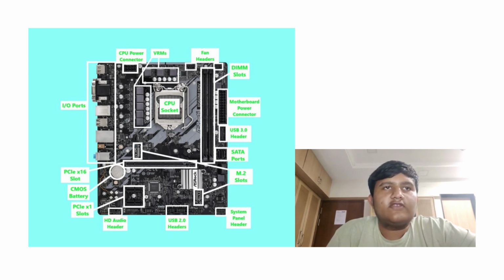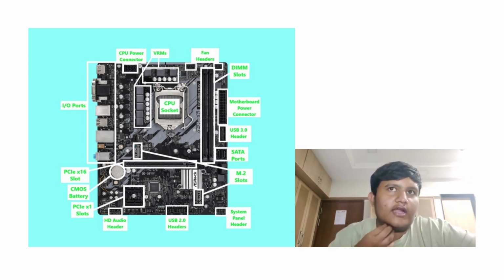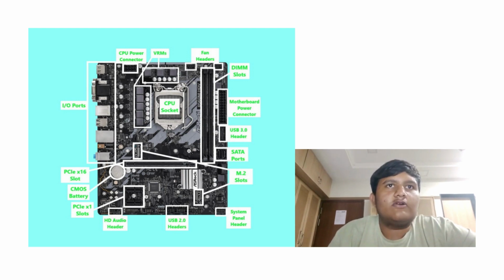Chips with high numbers of pinouts often use Land Grid Array, which is LGA, or Zero Insertion Force sockets, which is ZIF. LGA sockets apply firm force with a surface plate, and ZIF sockets apply compression force with a handle. Each method ensures that upon insertion, the pins are not damaged or broken. A CPU socket is specifically designed for a particular CPU and is usually not interchangeable with other types of processors.